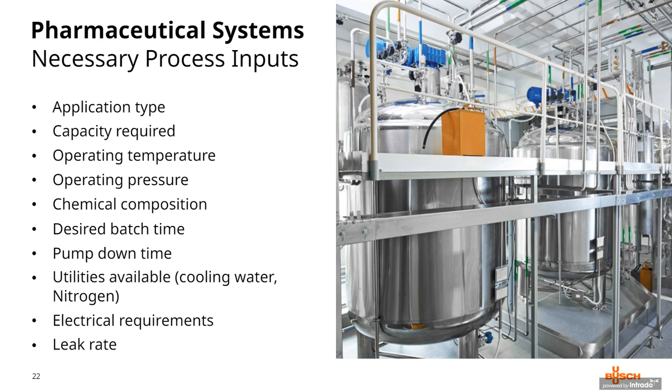While working with the vacuum experts, there are several important inputs which must be known in order to have a proper design. The general inputs are listed here, but there are a few that the designer needs to know for any system in order to properly design it. These include the required pressure and how to control it, whether you're using a VFD, a control valve, or some other means.